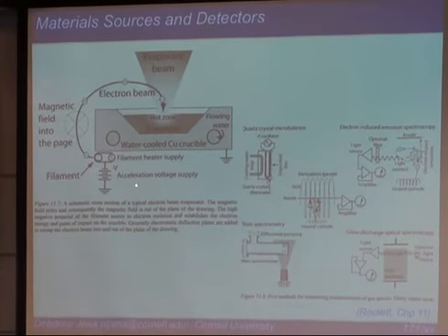Okay? And now what you do is essentially you have an electron gun, right? And a filament that, when you apply a very large voltage, electrons just boil out of it. Just like your atoms boiling out of that, here you're shooting electrons out, and you use a magnetic field to bend the electron beam and let it hit that refractory solid.